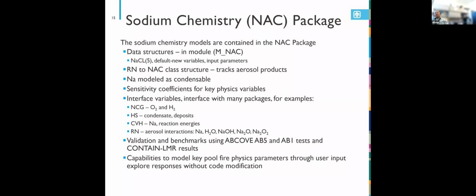The corium spreading models in the LWR were done that way. We did it in a control function first, and once it looked okay, then we implemented the model. There's a reason to hardwire into the code, because some of the properties you don't have to include in your input. You basically use the properties already in MELCOR, so it's a lot easier and faster.